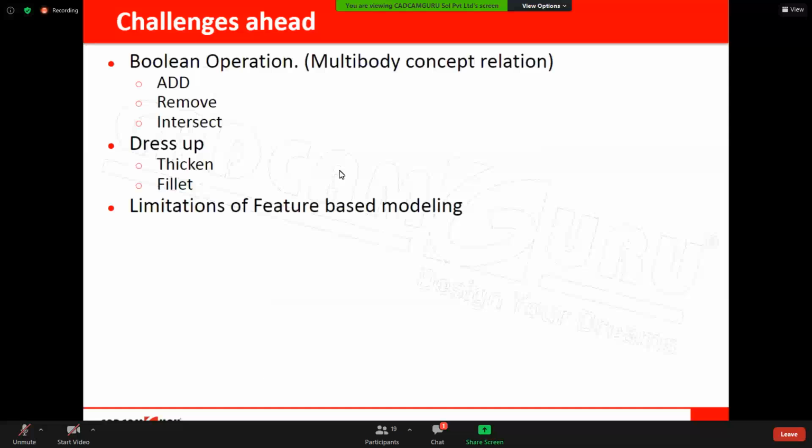Now let us understand why to use Boolean operation. From an application point of view, your answer is correct. It is used in plastic and casting products. But why use Boolean operation? Before understanding that, let us understand what feature based modeling is. The earlier modeling which was created in Catia, that modeling method is feature based modeling. That is the nature of all software. Creo and NX also have a feature based modeling approach.